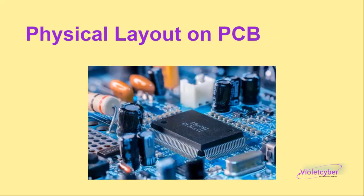Physical layout on PCB. The placement of capacitors on the PCB is important. Bypass capacitors should be placed close to the power pins of sensitive components for optimal performance. Also, the trace between the capacitors and load should be short to reduce the inductance effect.